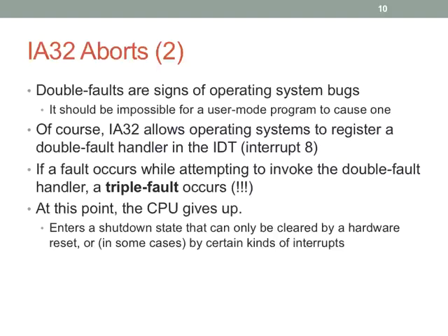What happens is either the system resets itself, it does a hardware reset, or it waits for a user to do a hardware reset, or in rare situations, like on a multi-core system, you can have one core try to reset another core. Because obviously all of this is an interaction between software and hardware, but it's an execution path. So if you have multiple cores, you might have one core that's flipping out and another core can try to reset it.